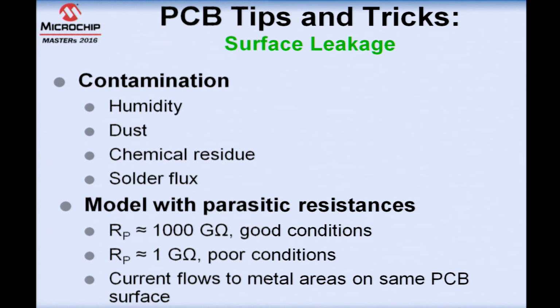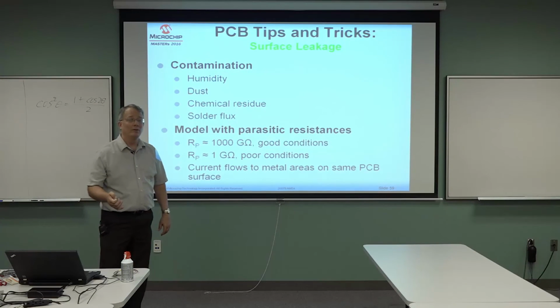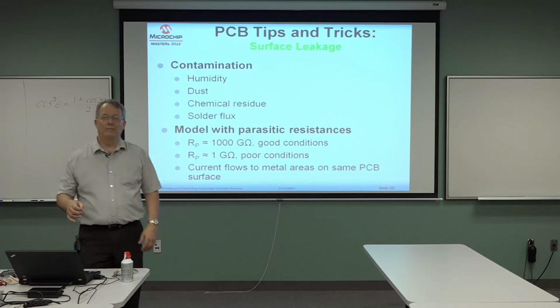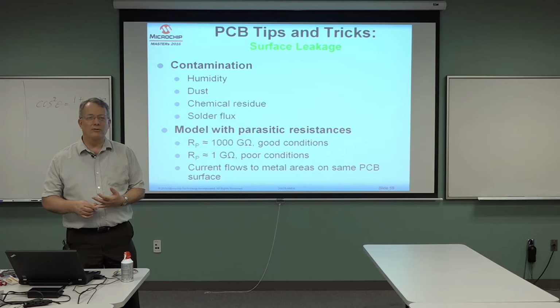That's a problem. Another problem is dust. Dust collects. What's not well known is that any electronic component, say my laptop, is exposed to the output air because the fan blows air out. Because I have voltages in here, I have voltage gradients in the air, and those voltage gradients attract metallic dust. Dust that has a higher metal content, which conducts more. It doesn't attract pure silicates, standard sand, for instance. It attracts the type of dust that's going to cause a problem for your electronic system.